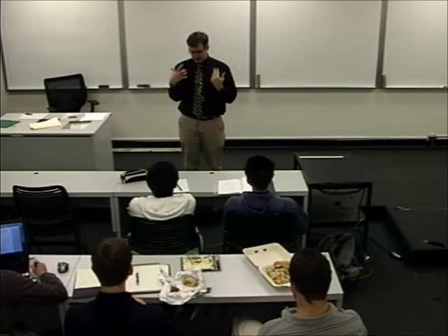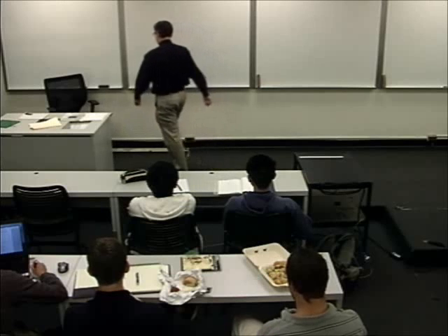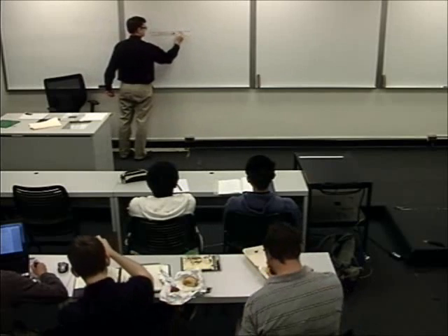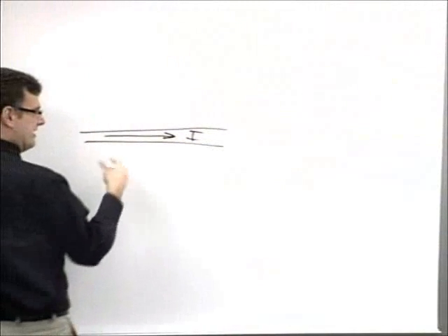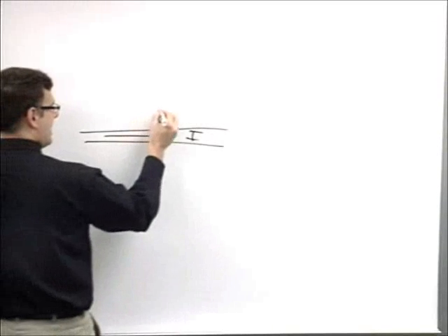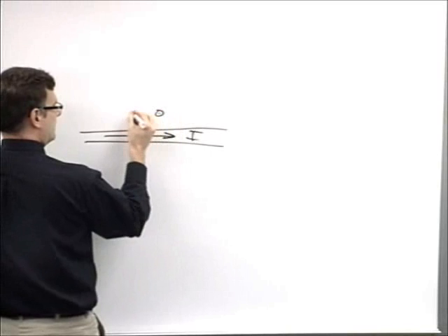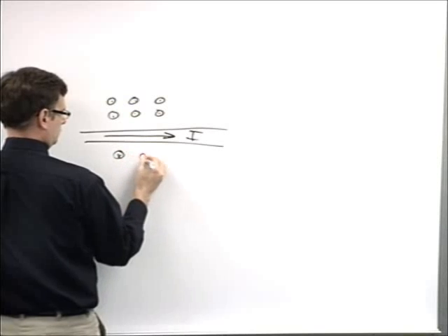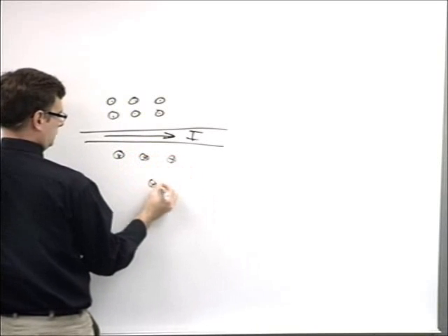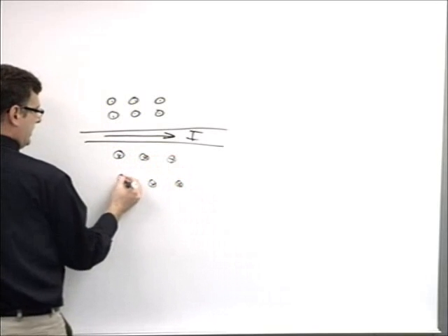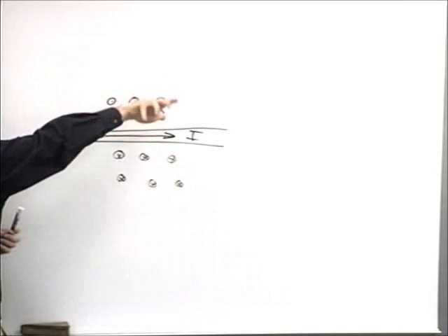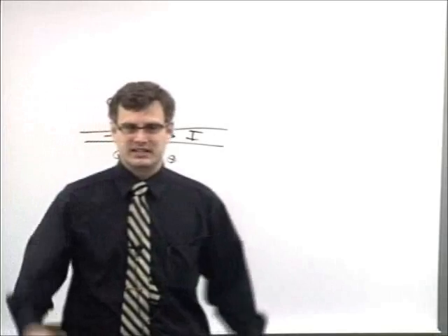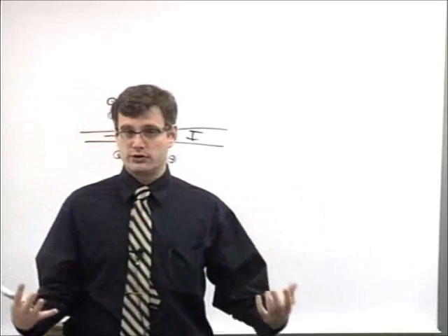And one way to think about inductance is a sort of current momentum, right? If I have a wire with current on it, that has a magnetic field around it. If this is a magnetostatic current, it will have, coming out of the board up top, and going into the board at the bottom, a la the right-hand rule. And if this is a DC current, there's a static magnetic field that sets up around the wire, and it represents a stored energy.